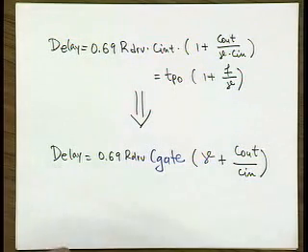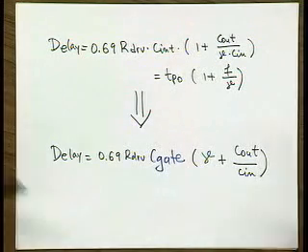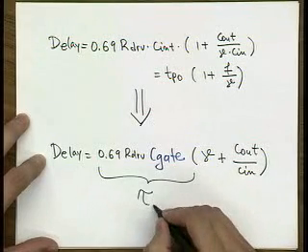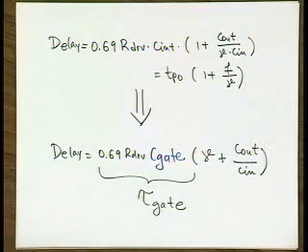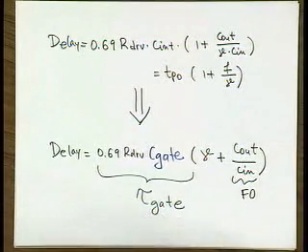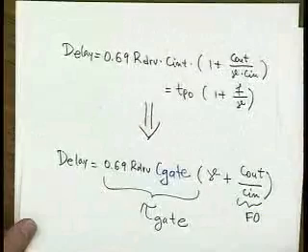So it's basically just saying that C intrinsic is 1 over gamma times C gate, and then we do it here. And then this parameter over here, I'm just going to say that this is tau gate. That is some time constant for a gate. And this is simply the fan out. People use various notations, H, F, that's a fan out. FO. So now let me go one step further over here. Everybody happy with this so far?